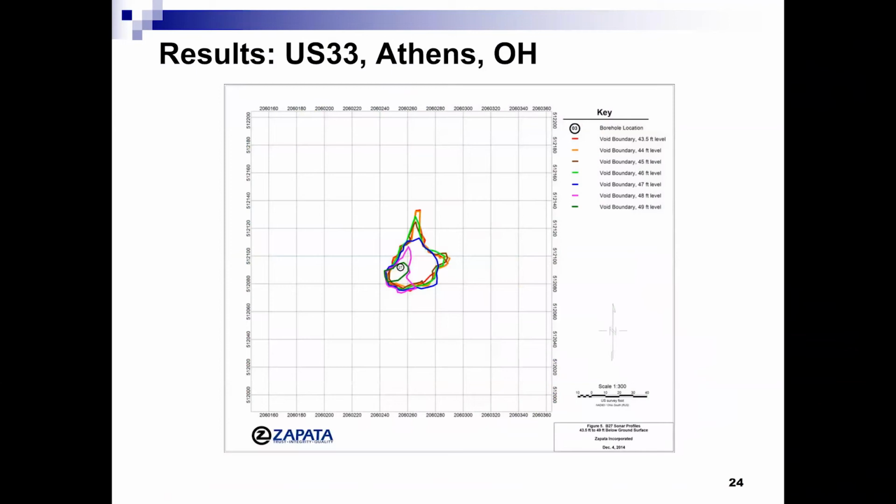Some locations are like 40 feet long, 40 feet lateral, but very shallow, very thin in the vertical dimension. So it's a very thin void. We found that we can go up to probably 3 diameters of the void with the depth. If you have a 10-foot void, we can identify down to 30 feet depth. Deeper than that, we don't see it very clearly, but we see a soft material joint, so we can still identify probably down to 5 diameters depth. In this case, the lateral dimension is large.